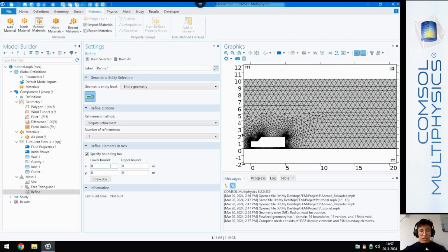And for this, essentially, we're just defining 2 vertices that form a rectangle. You can imagine one vertex here and then another one here. And essentially, they're going to form a rectangle, which is what we're going to define with. And we can use some of the parameters that we defined before. So for example, for the x, we're going to set it to negative front padding. Front pad, this is the padding that we have set as our parameter. Then for the back, we're going to have the car length plus the back padding. For the y, leaving it at 0 is fine. And then for the top padding, we're going to have the car height plus the top padding, like this.